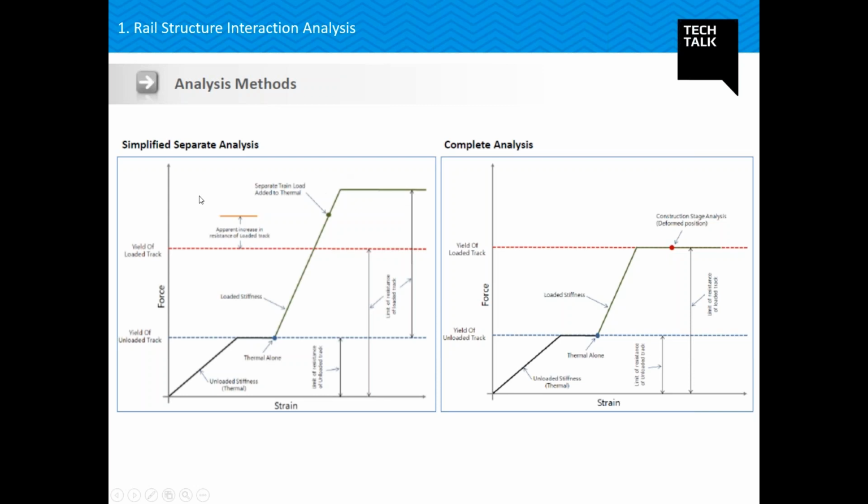So the total stiffness here will become 75. However, the total stiffness of my ballast is only 50, and that too in loaded condition. So this increase in stiffness means it will take the stiffness of ballast on a higher side. This will give rise to higher stresses in my rail. So this may be a more conservative approach. However, if I apply the same loading in the same model, it will not breach the stiffness of the ballast which I have defined. So here it is more of a realistic kind of analysis.